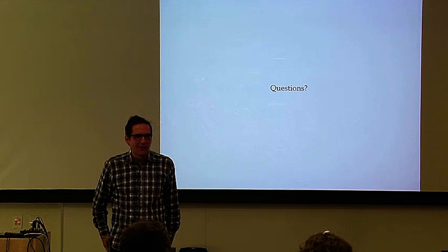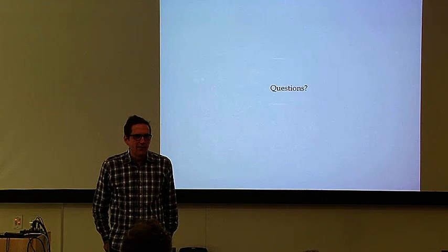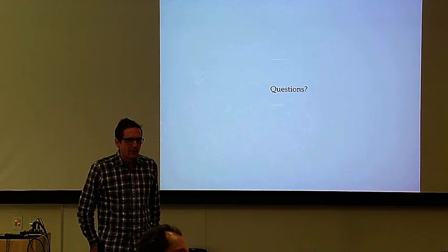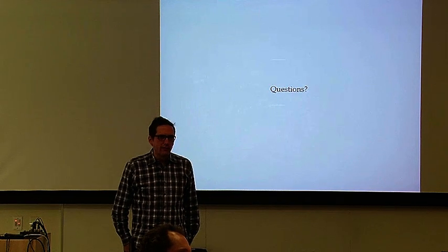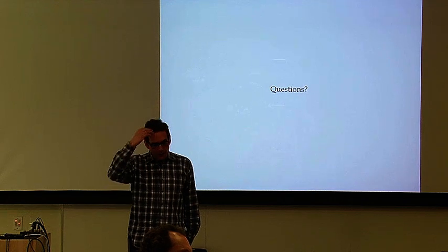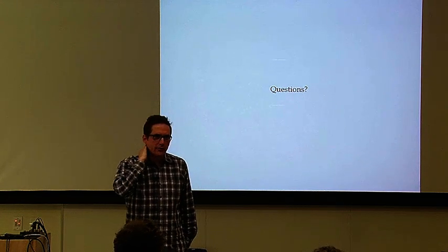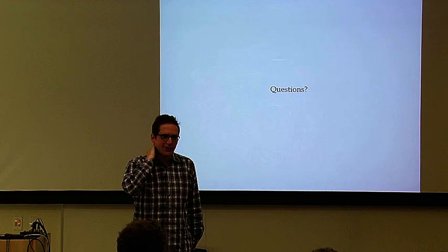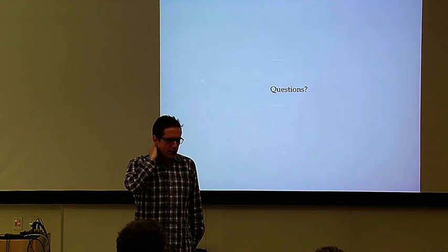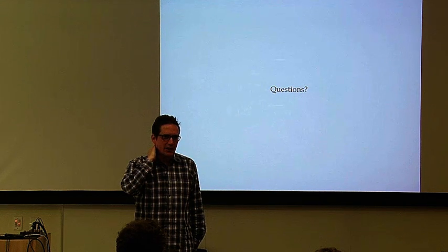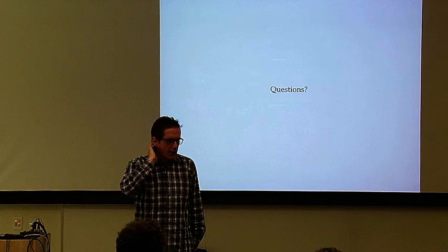Yes. Well, I guess I was saying, since your advice was see how much you can pack into a microcontroller, what kind of compromises did you make when you started running out of horsepower? Well, the first thing is to choose a microprocessor, which is really difficult. I mean, there's so many out there, right? So the first thing I was looking for was one that does floating point quickly, because I knew this would be key, and it's not just the clock rate.